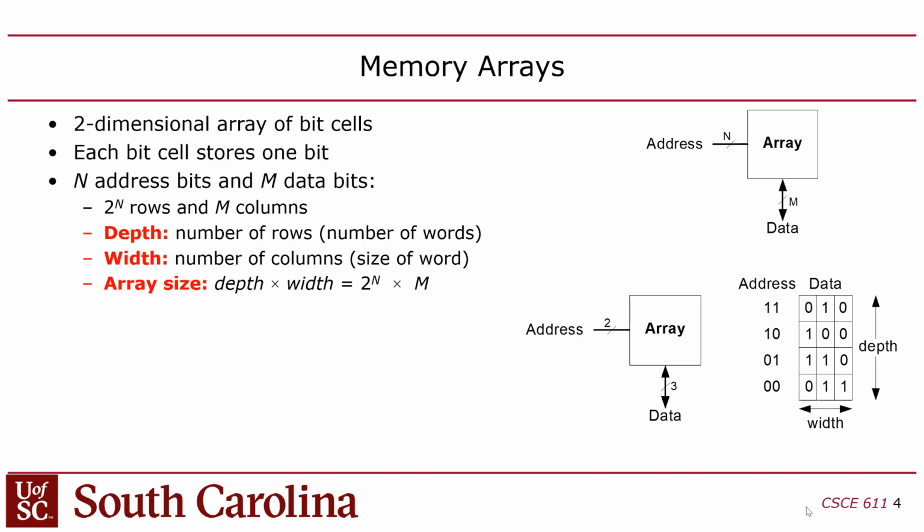Okay. RAMs can have whatever geometry in terms of width and depth. The depth is the number of unique addresses that are in there, the unique locations, and the width is the number of bits you read or write at one time, right? The depth is usually listed first, and the width is listed second. So if I have a 1024 by 32, right? What is that? 4 kilobytes, right? Because 1024 deep and then 32 bits wide is 4 bytes. So that's a 4 kilobyte RAM if I say 1024 by 32, right? Okay.